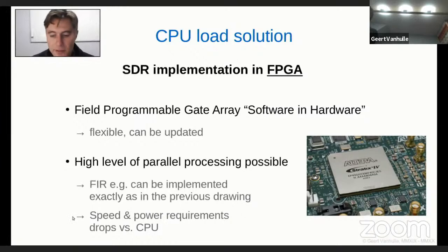Now, let me switch to a note here. The thing is that today, FPGAs are in no way optimized for software-defined radio use. So if there is any candidate PhD who wants to work on chip design and make progress on FPGAs for SDR applications, there's a huge opportunity here. First of all, FPGAs do exist. Of course, you need mil specs or space specs. They need to be capable of handling a bigger temperature range, from a low temperature up to a high temperature. That is one parameter.